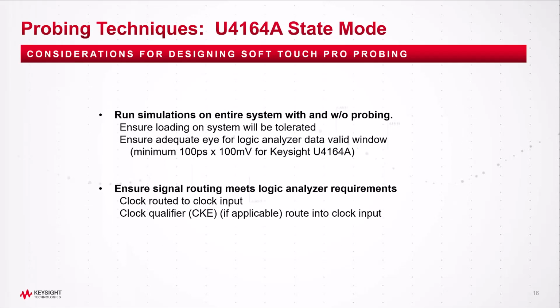Considerations for designing the SoftTouch Pro probing into your system. Run simulations on the entire system with and without probing. This will help you understand that the loading on the system will be tolerated and ensure that you have an adequate eye for the logic analyzer data valid window, the 100 picosecond by 100 millivolt for the U4164A at the SoftTouch Pro pads. Ensure that the signal routing meets the logic analyzer requirements. Clock needs to be routed into one of the 2 clock inputs, and a clock qualifier, if applicable, depending on the memory technology, routes into a clock input also.